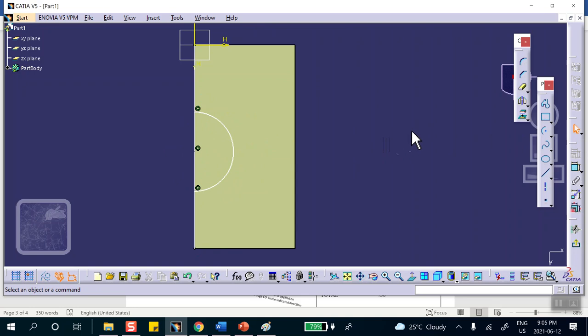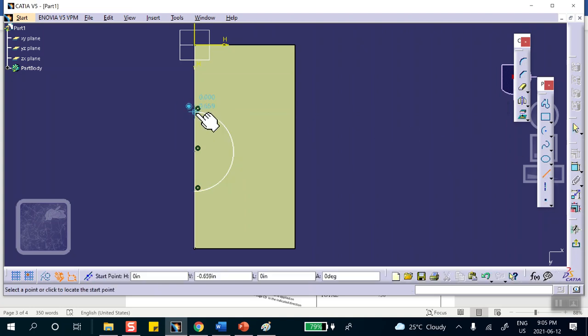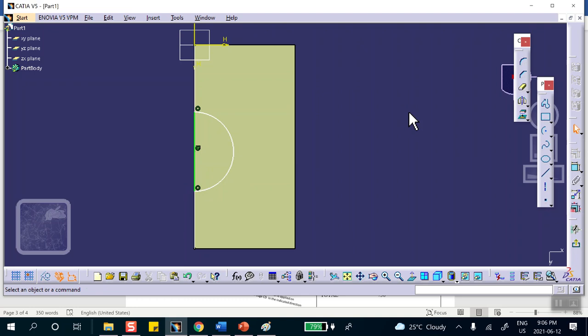Since I'm going to be cutting this top surface with that circle, we can see if we can cut it with just this arc, or we need to close it. My gut feeling is I think we have to close it because we're going to use the split command, but I'm not sure. I'll let you worry about it if you want to.